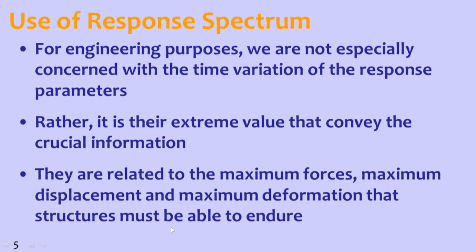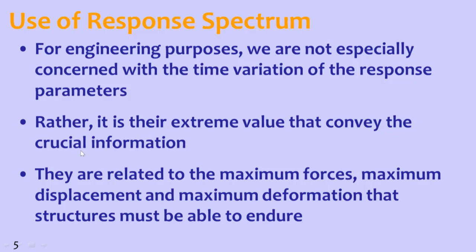Now, uses of response spectrum. For engineering purposes, we are not especially concerned with the time variation of the response parameters. Rather what we need is maximum responses. That extreme value conveys the crucial information. These are related to the maximum forces, maximum displacement and maximum deformation that a structure must be able to endure. So we need maximum values, and hence response spectrum is needed.